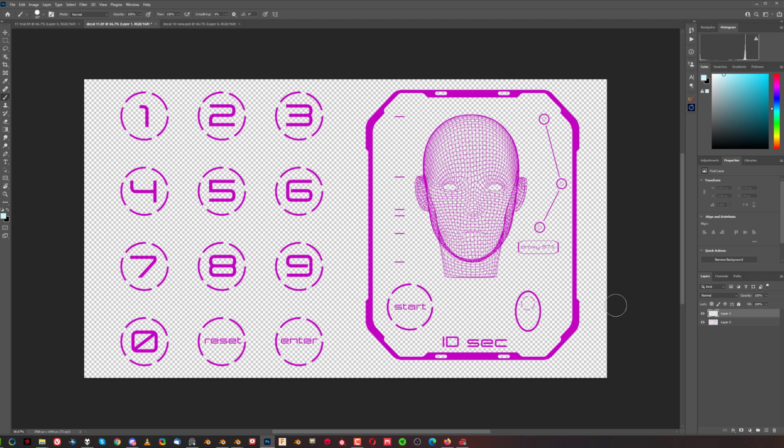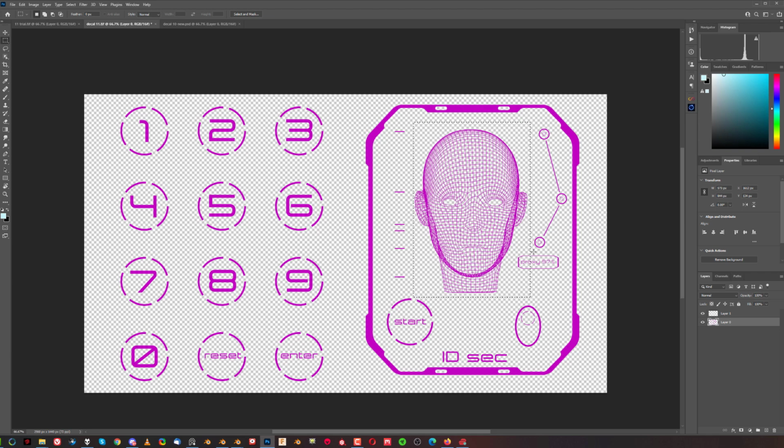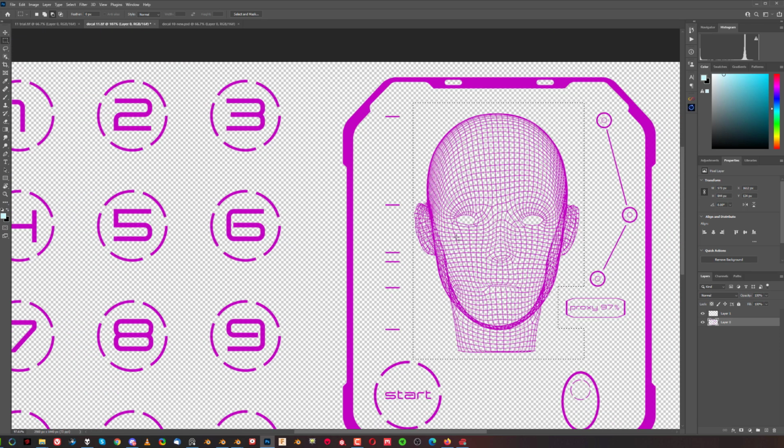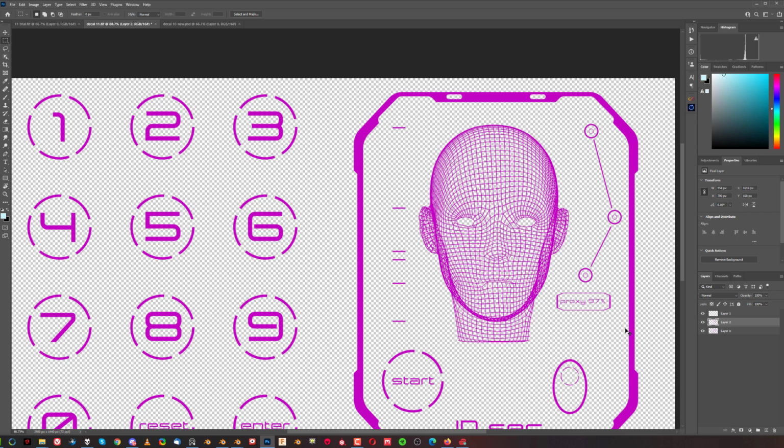But before we do that, I want to do a few things. First of all, select the main layer, and I'm going to trace around this face, but I can see that I'm going to be getting into the zone here. So what we can do is select it and then deselect part of it with either the lasso tool, or also with the box select holding Alt. Holding Alt will deselect, remove from the selection. This is selected, good. Okay, so now Control J to move this on top here.